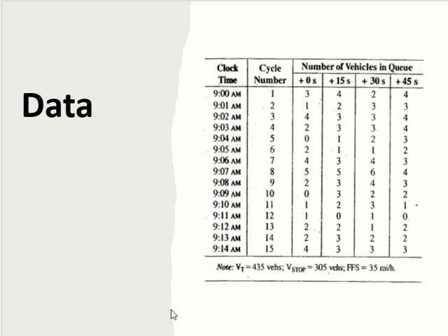So this is the data they were talking about. Again, you have the free flow speed, the total vehicles stopped, total number of vehicles and vehicles stopped, and these are the observations from the first observer. What is the interval here? 15 seconds. And what is the cycle length? 60, right? 15 seconds is each interval, and you have 4 values. So 15 times 4, 60 seconds. And again, you can look at the time as well. And how many cycles do we have?